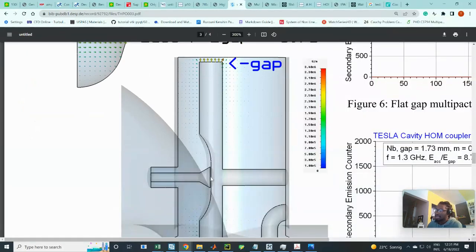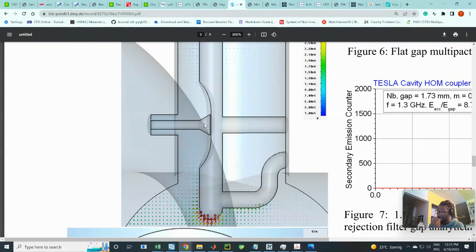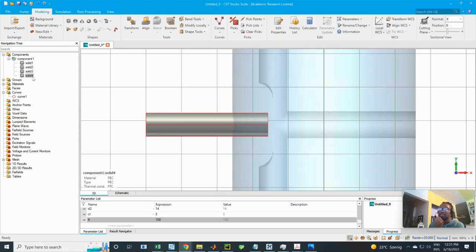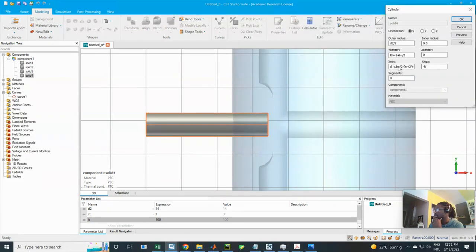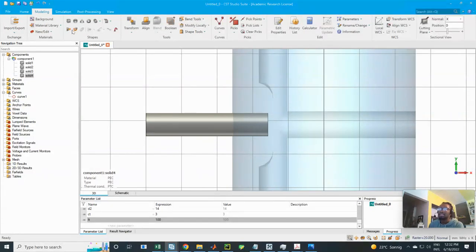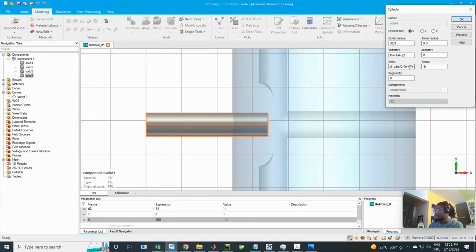Then I could copy the head style of this. And how would I do that? I would use a circle, and let me see a cylinder, and let me see if there's an option to taper. So there's no option to taper the cylinder. So I think for now, I'll just use a cylindrical head, and then I need some dimensions copied. So I need the x minimum instead of having to calculate it again.